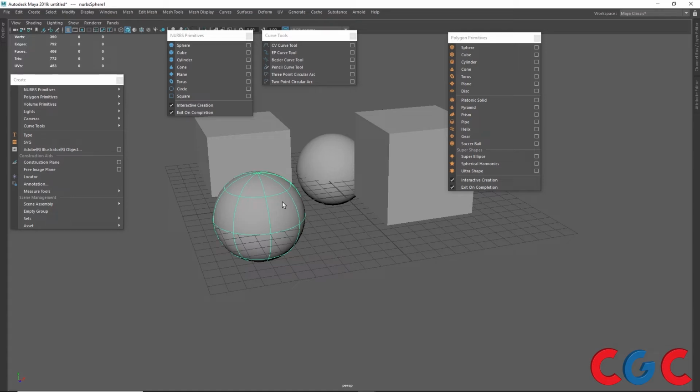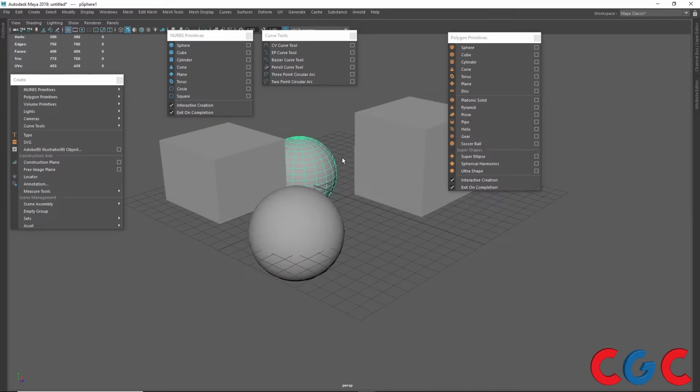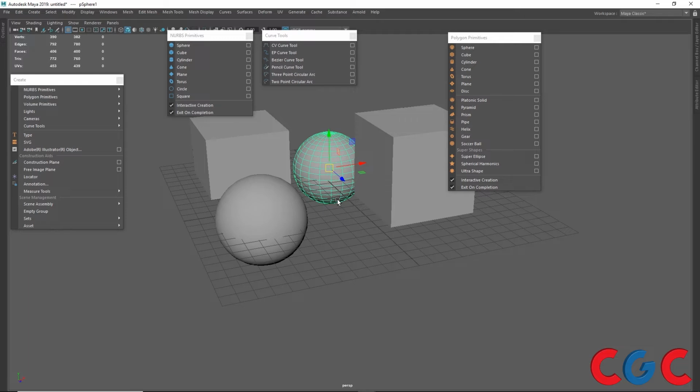This Nurbs uses a different technique when it renders, the tessellation method, where when the camera is near the triangles are high, and when the camera is far away, it will give you fewer triangles. This tessellation method is not available in polygon, but in other ways polygons are more comfortable when we are working for movies, games, VFX, where there is a pipeline, dynamics is involved, rigging, animation, those things are involved. So better we go with polygon.